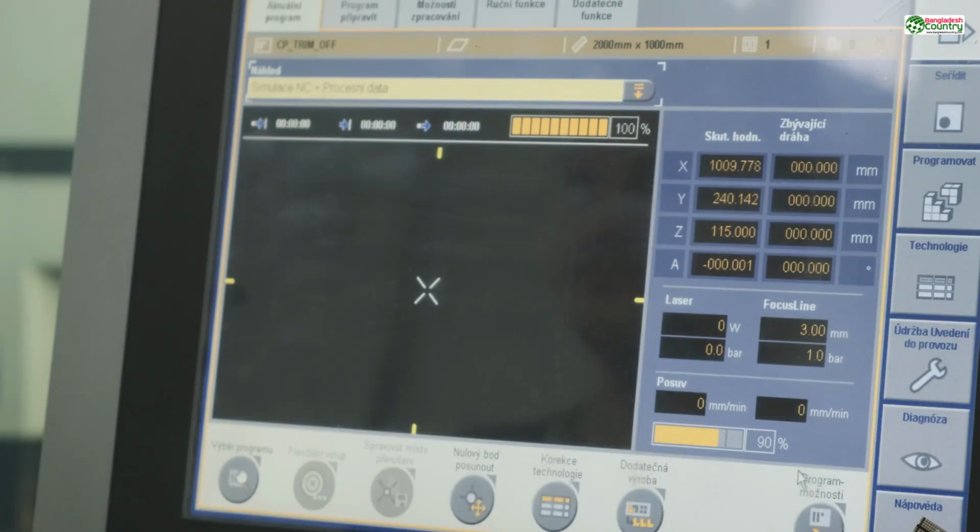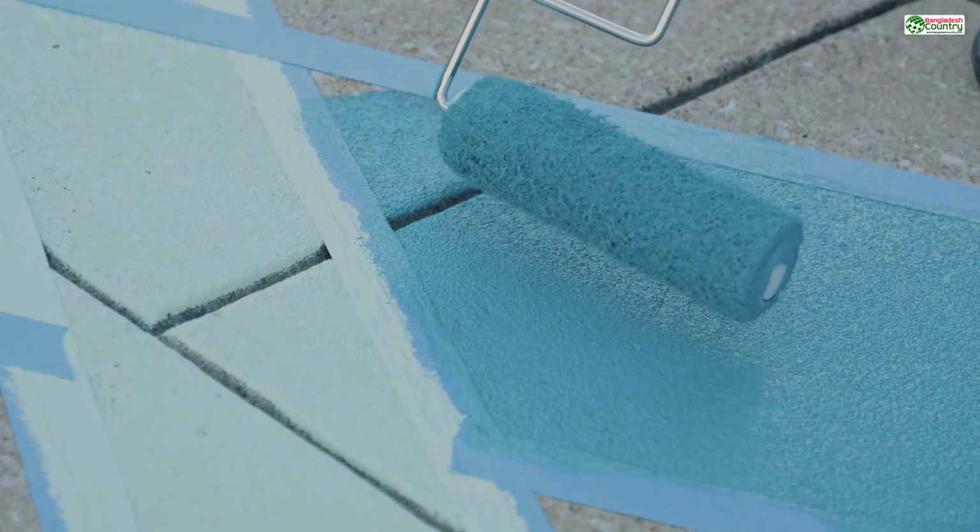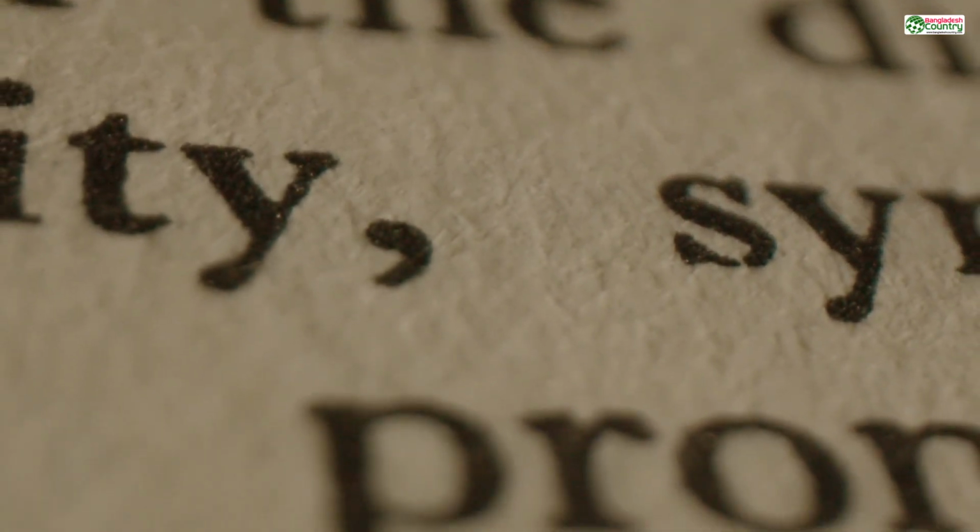You can enable a feature called Mesh Analysis that paints your model in different colors to reveal problems. It can highlight zero-thickness walls in red, or sharp, unprintable edges in blue. It's like putting on a pair of X-ray goggles that let you see the hidden flaws in your geometry.